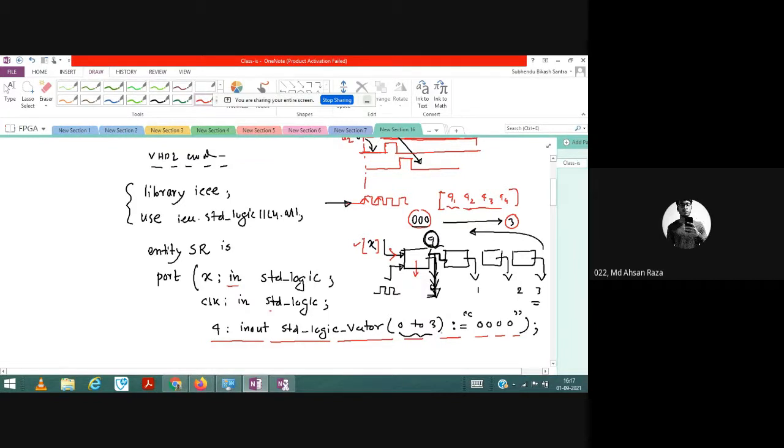And the initial value: let us say I am giving the first clock. Okay, so during that time what will be the output? After that, the output will change for each bit of operation. But the thing is that if you do not provide the initial output, then the system will be problematic, because the second flip flop output depends upon the output of the first one, and the first output will only complete when you have a rising edge of the clock.